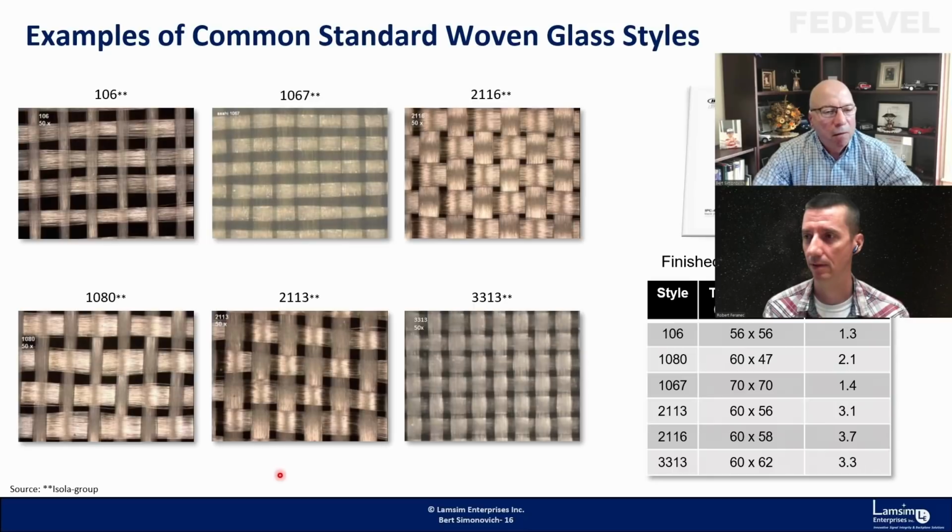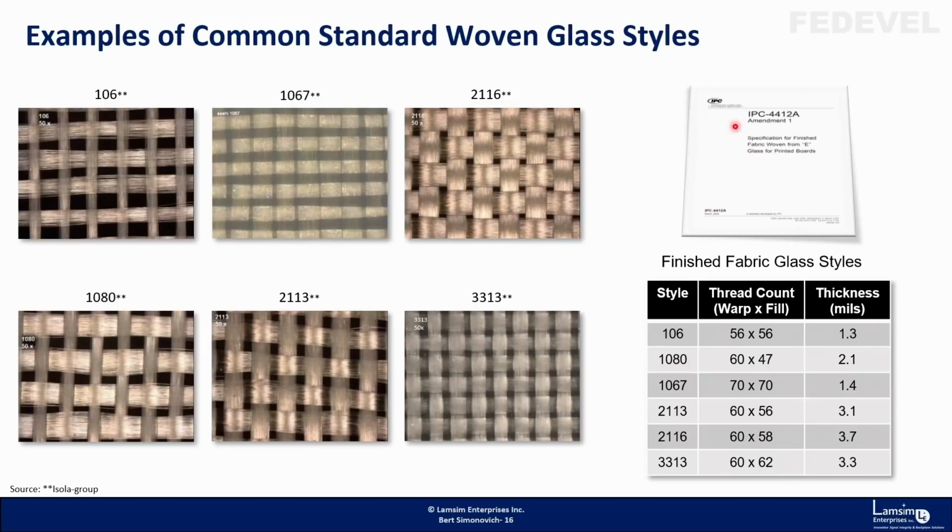Yeah, so the big thing as far as the dielectric material for high speed is the woven glass style. Here you can see examples of the fiberglass weave inside the laminates or the prepregs. They have different numbers associated with them, like 106, 1067, 2116. They're standard weaving numbers, and they're all outlined in this IPC spec, but really it means this style is a unique number.